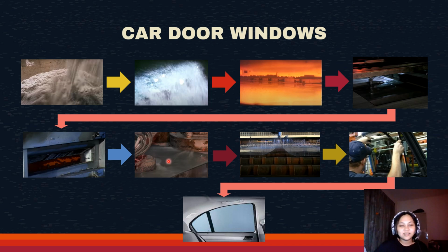The glass is then chilled rapidly to put a compressive stress on the glass, making it tougher to stand against massive impact. Thereafter, the glasses go through sag bending processes to be curved into the desired shape in pairs, where the glasses are heated to 600 degrees Celsius and are bent into a mold.